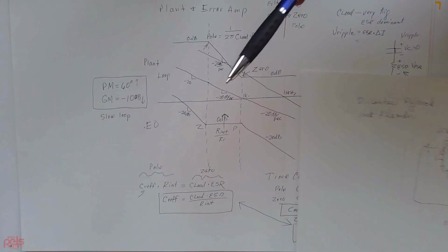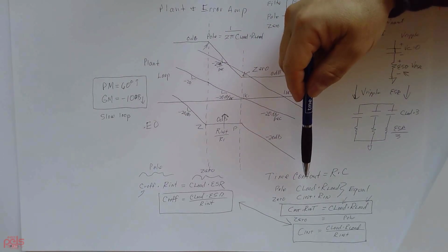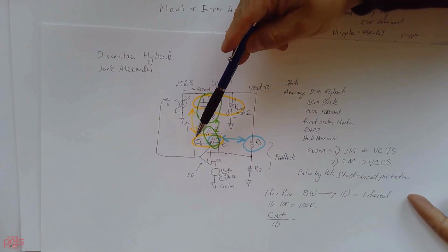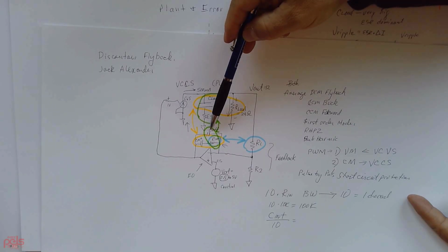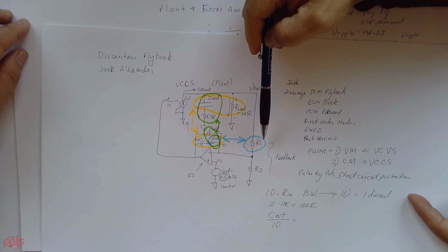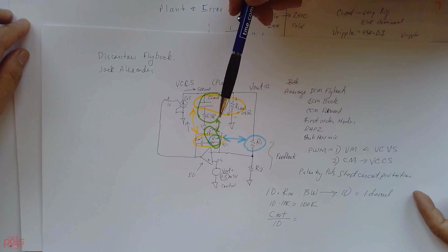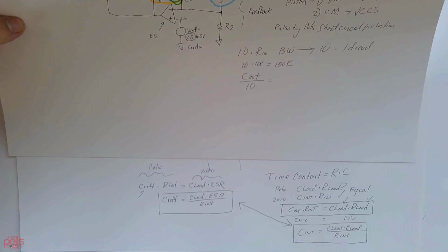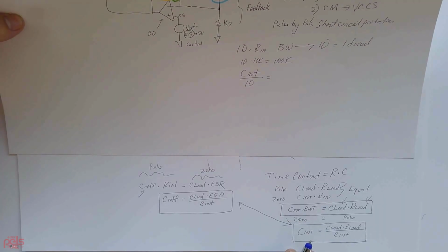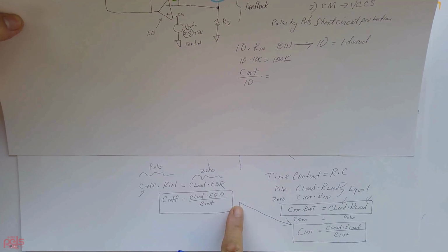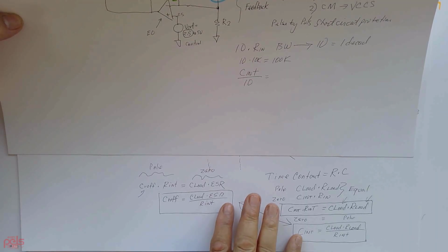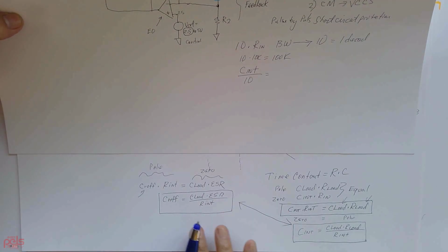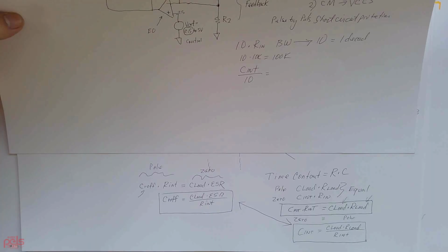Nice. And then this technique of cancellation, where we make the time constants equal, allows me to find C int, R int, and C roll off, and that's where I'm headed, right? Yes. If you forget anything, just memorize these two equations, which basically are your pole cancellation, and then you're set. Just these two equations will let you set your controller.